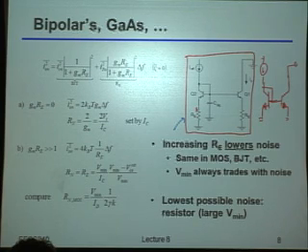Okay? Yes? Just to check, the noise that you get from RE, does it get canceled out somehow, or do you also get some noise from adding that resistor? Oh, so you were asking, hey, wait a minute, when I added this resistor, doesn't that resistor also add some noise? The answer is absolutely yes, it does. But notice, in the absolute limit, if I made this resistor basically infinitely big compared to the 1 over GM of that bipolar device, the noise of the bipolar device would completely go away, because the GM would be completely source degenerated.